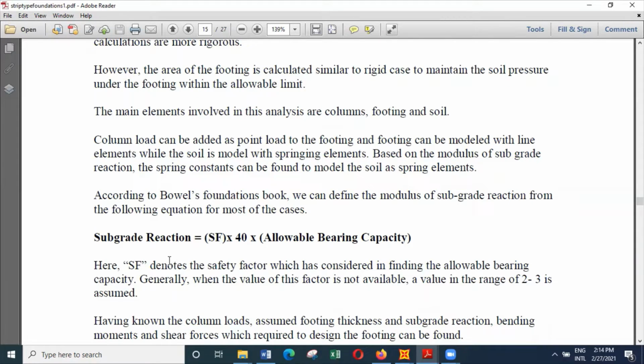The units of modulus of subgrade reaction are kilonewtons per meter cubed. Once you multiply the modulus of subgrade reaction by the area of the spring that you represent in the model, you can see how much the soil is going to deform vertically when you apply a 1 kilonewton load.